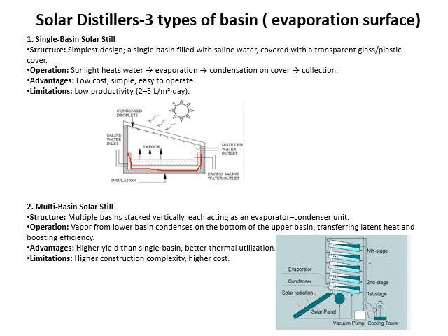For the multi-basin solar still, it is using a solar collector. The sunlight is heating up the water inside the solar collector, going to the first stage. When the water evaporates in the first stage, it will go up and condense, and it is designed in such a way that the second stage basin is linked to the condensation surface of the first stage.